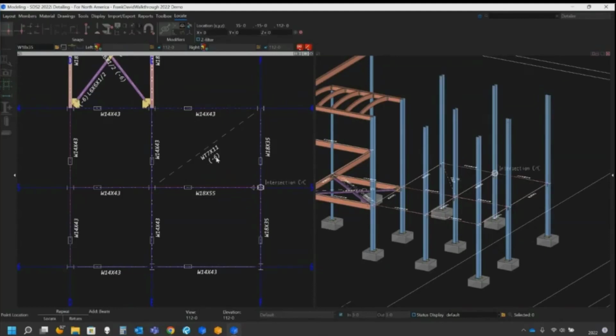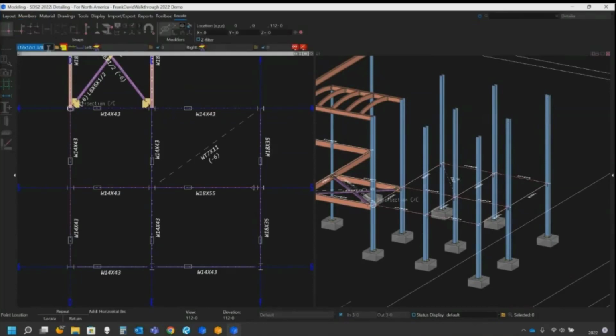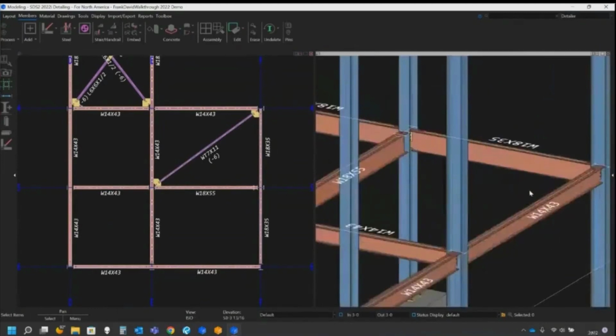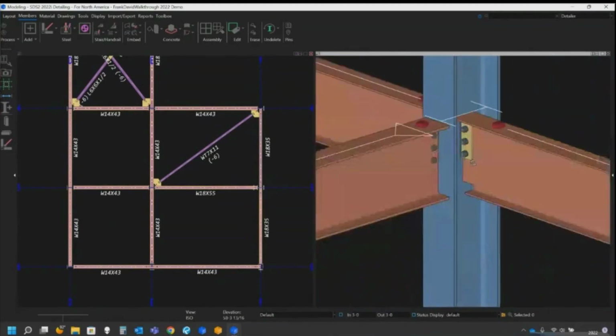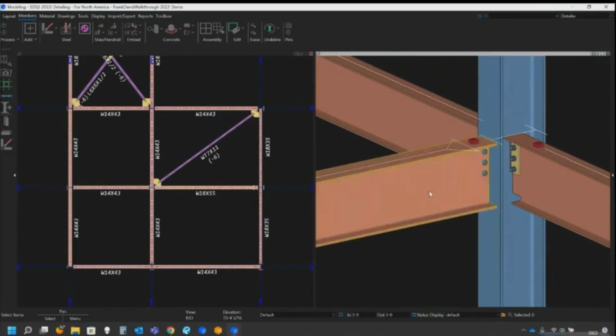Okay, and then I can input my horizontal brace there, the WT 7 by 11. Notice it's a -6 inches down, so I use my little Z offset up at the top here to punch in -6 to get that horizontal brace in the correct plane. And again, as I modeled it, you're going to notice that all my connections are designed. Everything is designed to AISC standards.